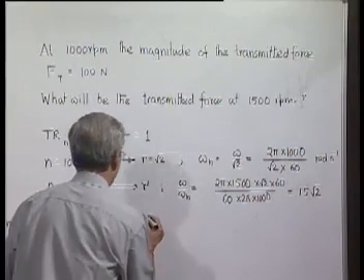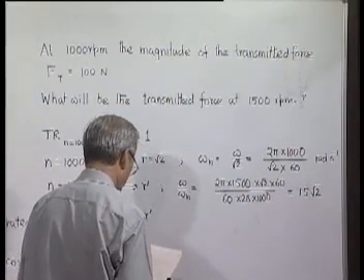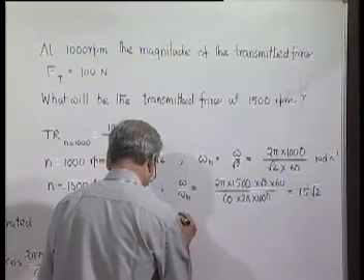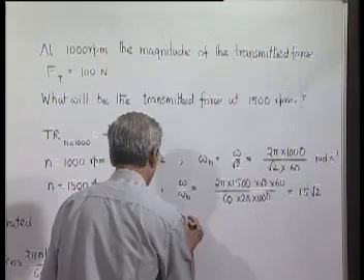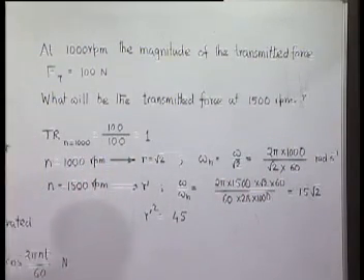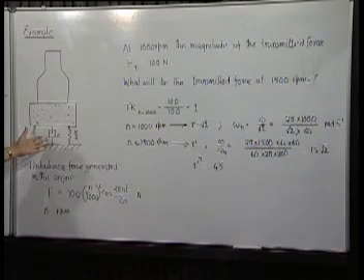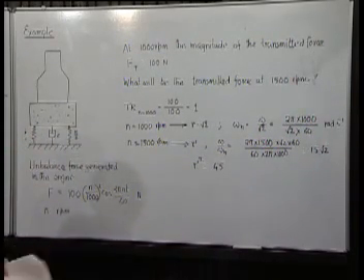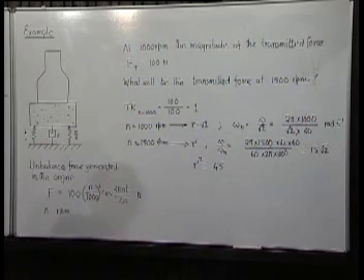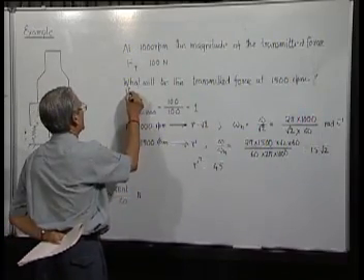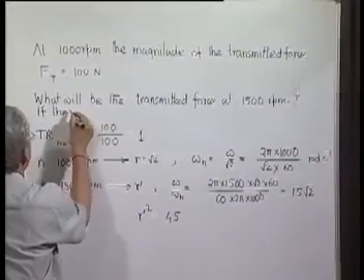r prime square equal to 4.5. Now, one point which was missed when we mentioned this: if we just tell r prime, we will not be able to solve the problem because C is not known. So, the only possibility in this case is that we can find out the transmitted force at 1500 RPM if the damper is disconnected.